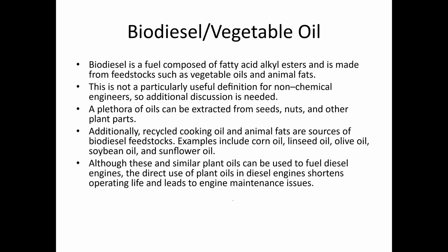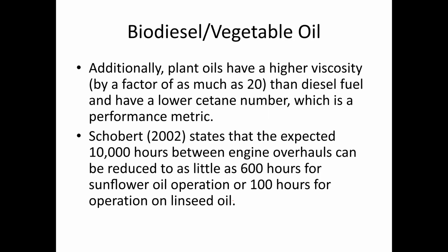Also, plant oils have a viscosity higher by a factor of almost 20 than diesel fuel and have a lower cetane number, which is a performance metric used. A study by Schober states that the expected 10,000 hours between engine overhauls can be reduced to as little as 600 hours for sunflower oil operation or 100 hours for operation on linseed oil.